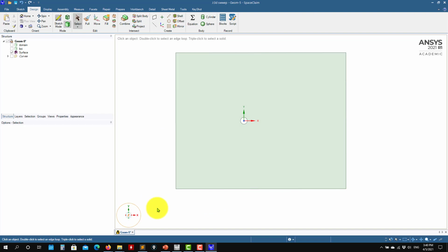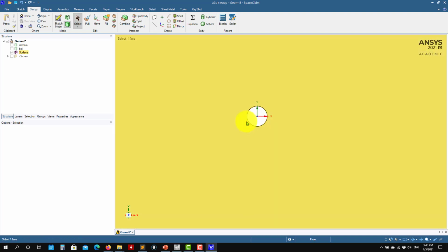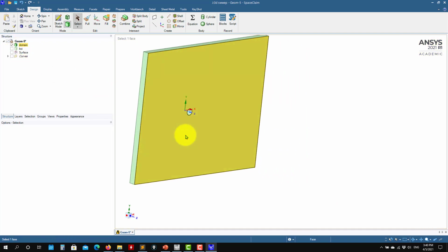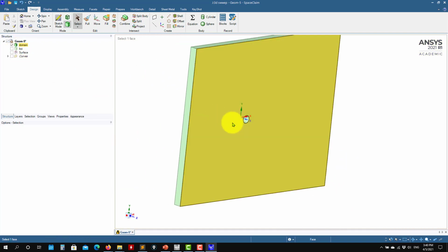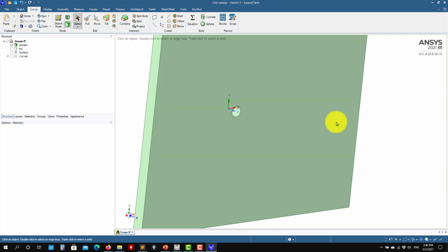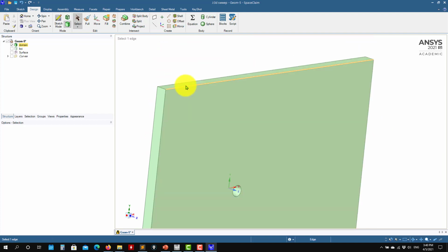We have seen that the Y plus value, wall shear stresses, pressure and everything can be plotted along a surface. But as you plot it here on the cylinder, as it is a line which doesn't have any thickness, it's difficult to visualize. So when you do it like this and do the extrusion, per unit depth, a unitary extrusion, now you have this surface and it's easier to visualize. That is why I prefer to do that.